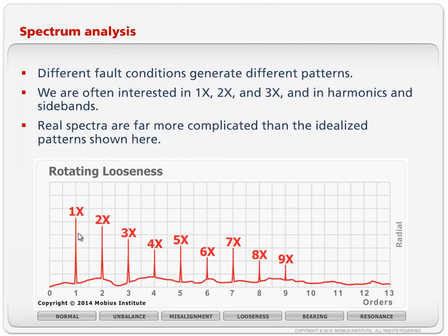When there is impacting going on or the vibration is not as smooth, just sort of distorted vibration, hard to summarize very quickly, instead of just one peak, we'll see 2, 3, 4, 5, and they may all be a similar amplitude. In fact, they might go up in amplitude or they'll go down. And we sometimes see the noise floor, the bottom of the graph, lift up as well. So, lots of different patterns.